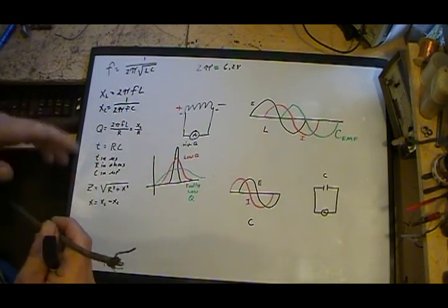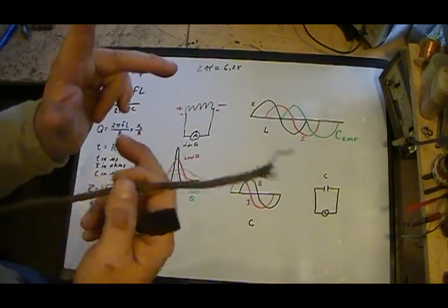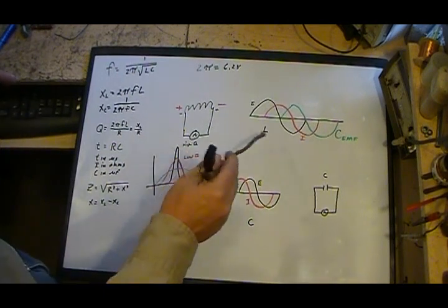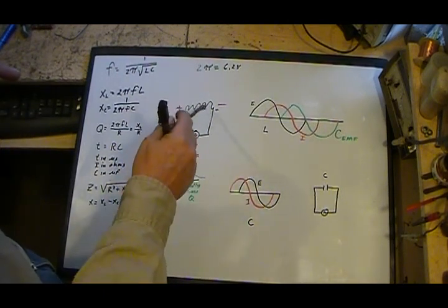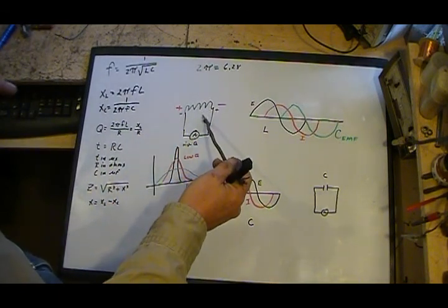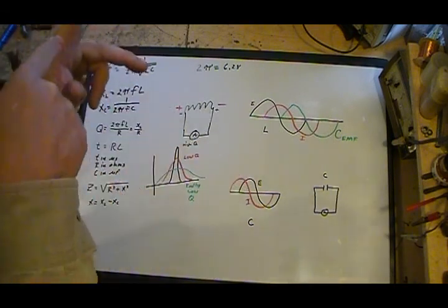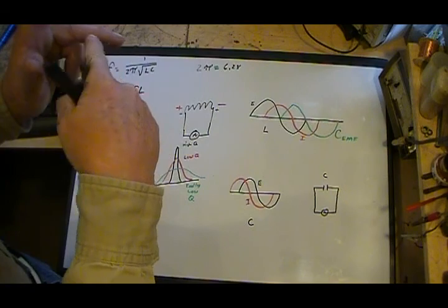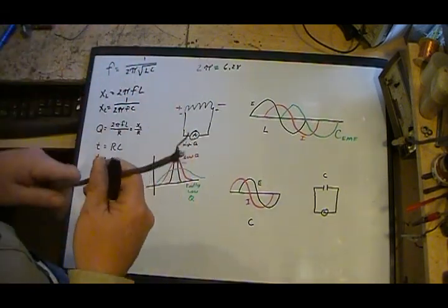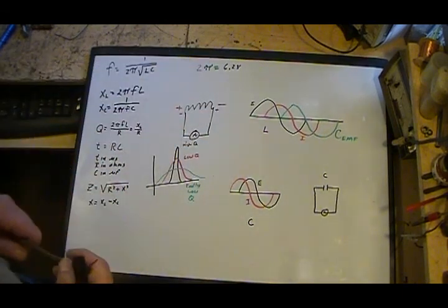Now, this is more or less the induction of voltage into a conductor, but it also works with how the counter EMF is developed, because as the AC signal goes through, it's building up a flux, so the flux is moving. If it's moving in this direction, the voltage can go this way and will actually be counter to the direction that you're supplying it.